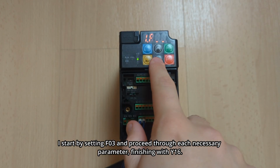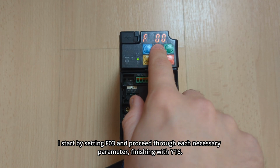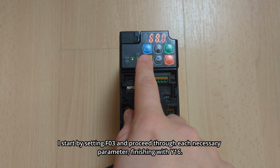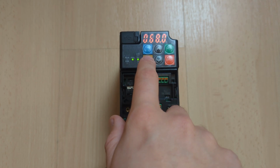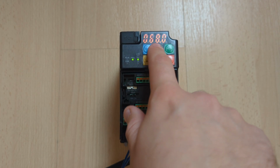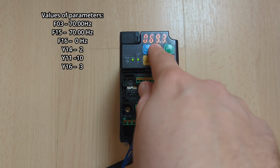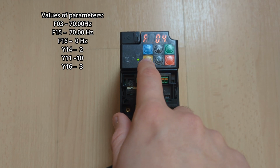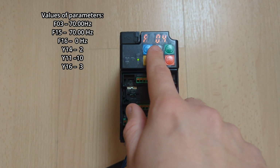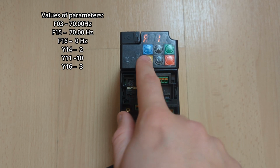I start by setting F03 and proceed through each necessary parameter, finishing with Y16. Values of parameters: F03 70.00 Hz, F15 70.00 Hz, F16 0 Hz, Y14 2, Y11 10, Y16 3.